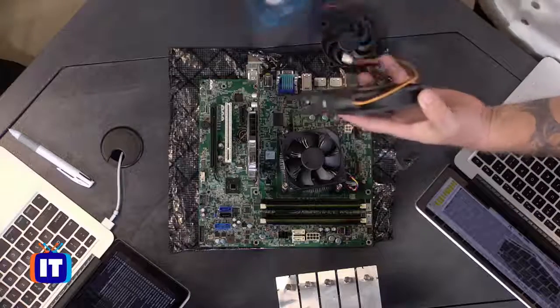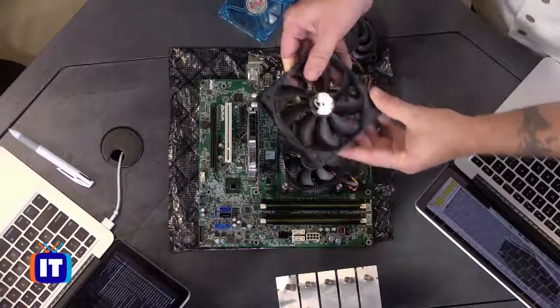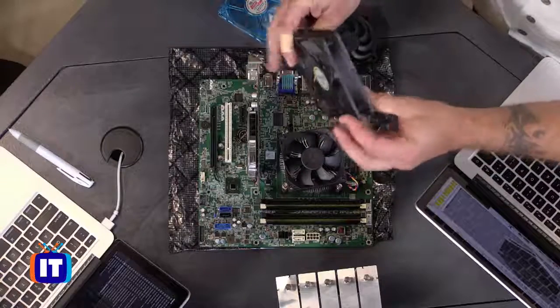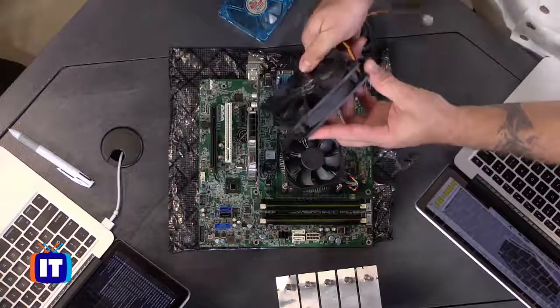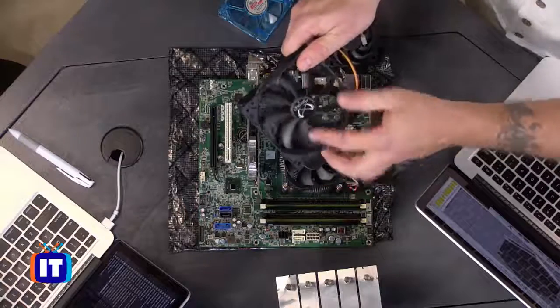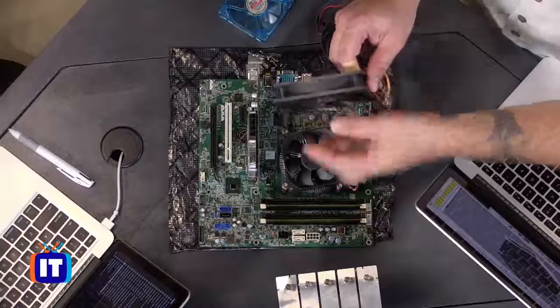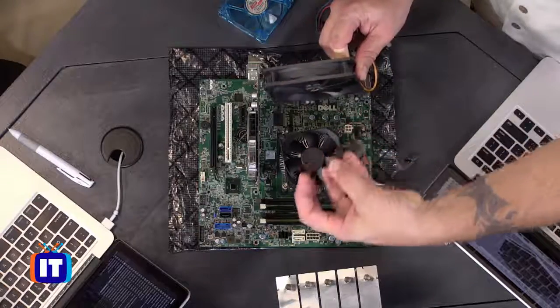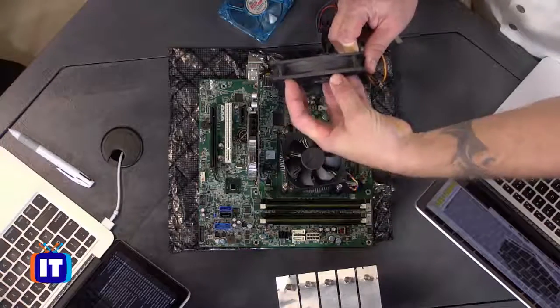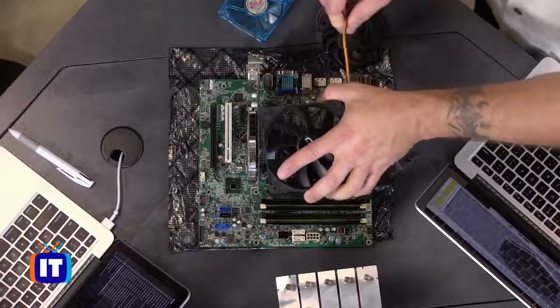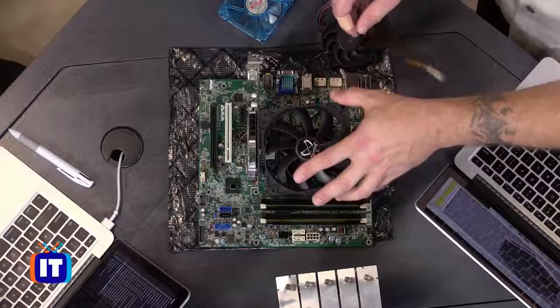Again, you'll have to pay attention. I don't know if this one has it on it. Usually you can see on the top somewhere, and yeah, I don't see it on this one, you'll have directions that show you which way this spins. And you've got to keep in mind that on the front of the case, due to the ATX standard, it's an intake fan, so it draws cool air, and as the heat rises, the rear fan is typically an exhaust fan, so it's a pull-push system, if I said that right.